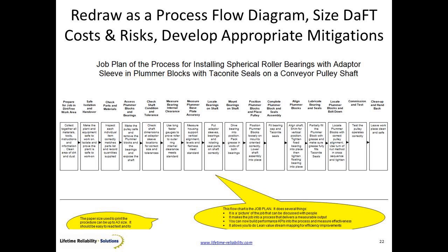Now I've taken those 16 steps into a flow diagram. In this particular way here, I can begin to see the interaction and the effect each milestone task has. Now, if I get that wrong, then that machine will fail earlier, sometime in the future. Now, if that's not done right, or I leave it out, it's very clear now. That's a series process. At the end here is meant to be a long-lived machine with 5 or 6 or 10 years trouble-free operation. And I don't do that well, or I don't do this well, or I don't do any of them well. I'm never going to get my 5 or 6 years.